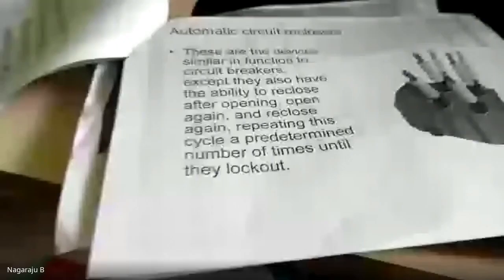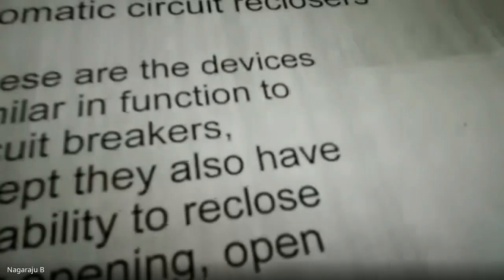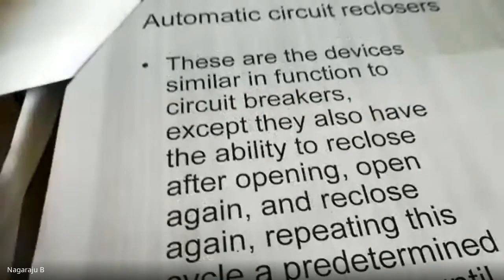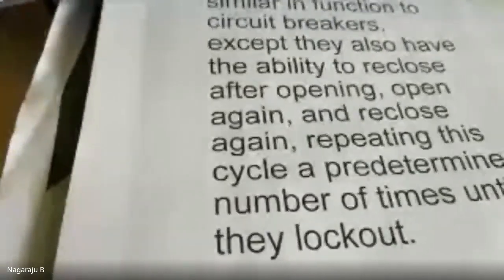The recloser must be able to interrupt asymmetrical fault currents related to their symmetrical rating. Are you following? So the minimum pickup for all ratings is usually set to trip instantaneously at two times the current rating.